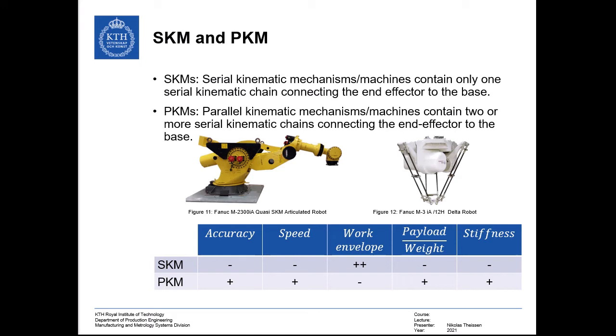You can think of the spot welding application of a car, or which don't require any precision in big workspaces and are subjected to high external loads, as for example pick and place applications, where it isn't necessarily important that it is actually positioned accurately within 1 millimeter, but the object that you might want to lift weighs a couple of 100 kilograms.